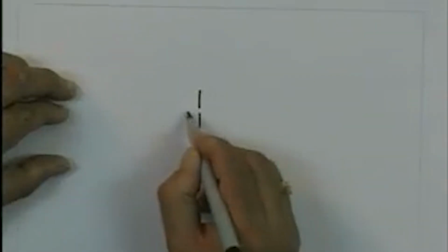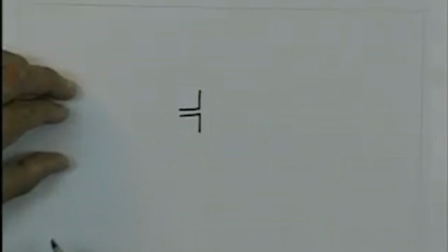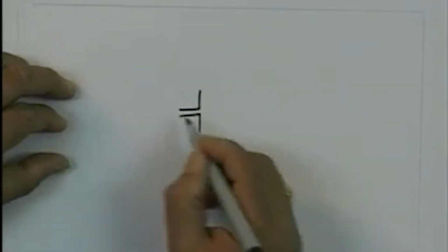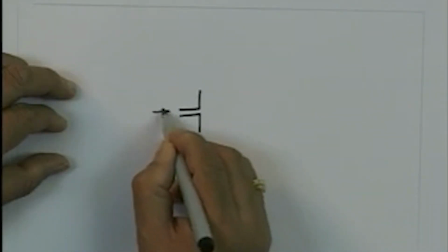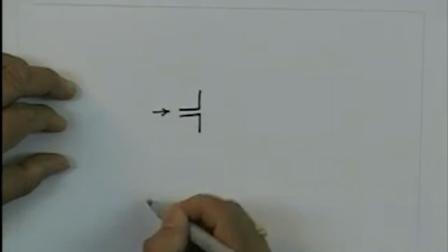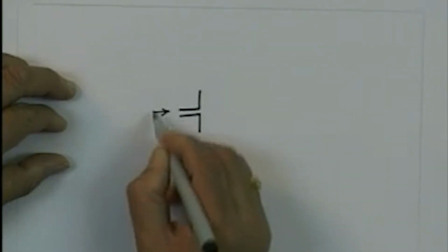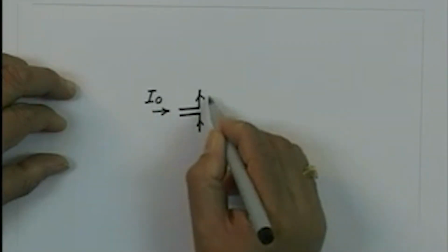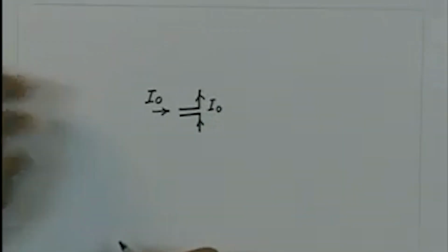Now, if I look at this antenna from the circuit point of view, the Hertz dipole, we can excite this antenna by some voltage source which will give me the current in the terminals. So, let us say if I break the Hertz dipole halfway, so this is my Hertz dipole now, which is broken into two parts, and this is the input through which the current is flowing. So, if this is connected to a circuit, the current I0 comes like this, it flows through that, from here it comes back. So, you have a current I0 flowing in the terminals of the antenna. So, this current is I0.